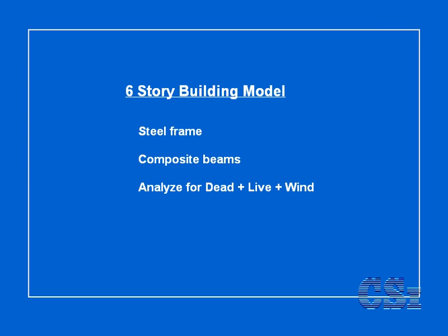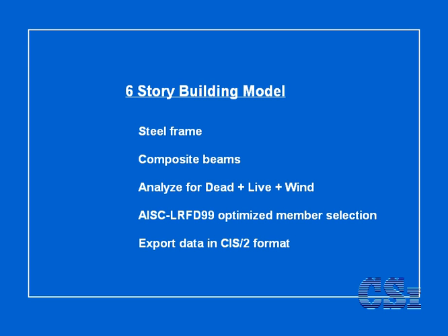It will be analyzed for dead, live, and wind loads. Members will be selected by the program based on least weight using the AISC LRFD 99 code. And finally, the data will be exported out in the CIS2 format.